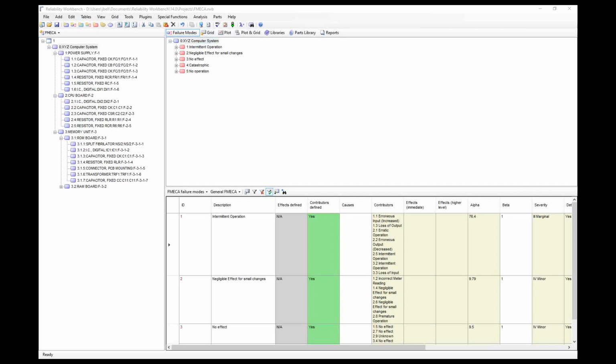We'll start with the FMECA. That's our baseline, our jumping off point to understand how this analysis type works. The point of all three of them is to examine not just the failures of a system, but the failure modes and their individual effects. In many other analysis types, we consider a component failure as an input to the system. With FMECA, we're not looking at just the failure, but how does it fail? One component can have multiple failure modes, and the results on the system of those different failure modes can differ. For example, one failure mode could be significantly worse than another one.